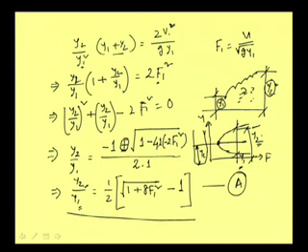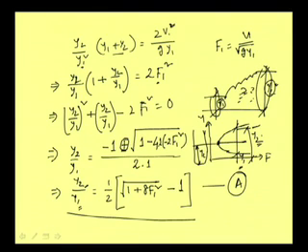But in that case, we will have to start from the very basic principle that specific force at upstream and downstream are equal. That is what we are writing here. Based on that, we will have to start, and then from there we need to compute the depth. Once we know the upstream depth, we can compute the downstream depth, and that we can do by a trial and error procedure for a trapezoidal channel.